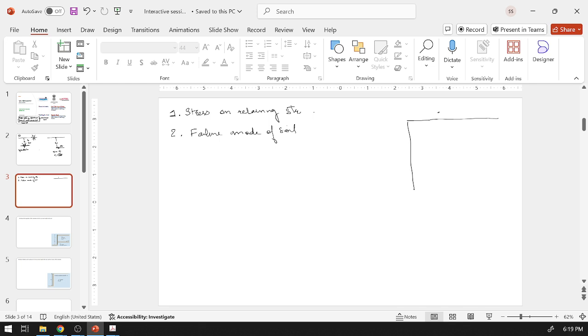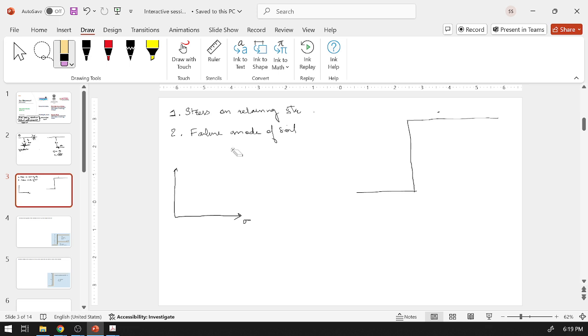So why this is important is you have to understand that until now, whatever you have been studying, say, like in strength of materials, you draw a stress strain curve. Let us say, for example, you study steel, you have this kind of a curve. You have a yield point here, and you say that the material is elastic in this region and it is plastic in this region, where the stress has surpassed this yield point.